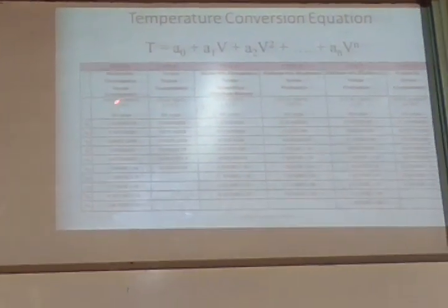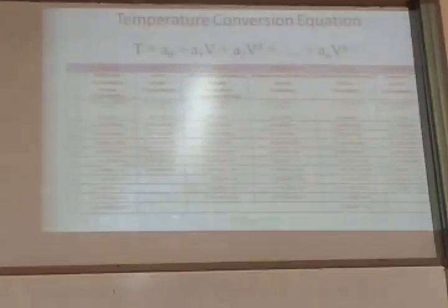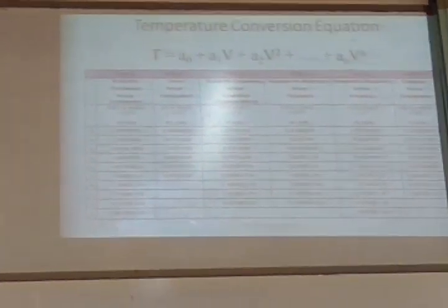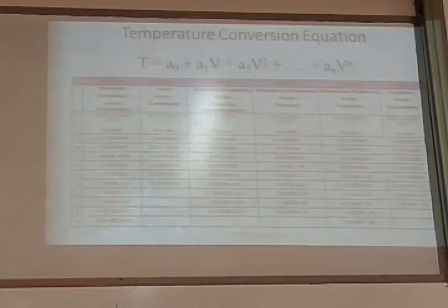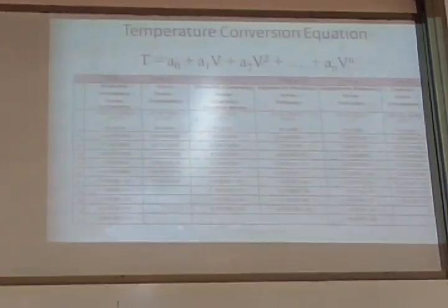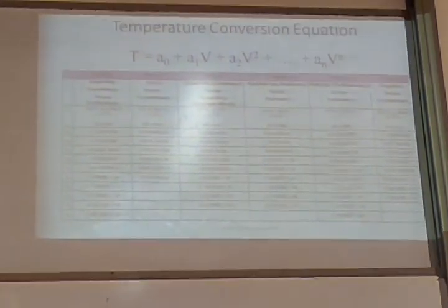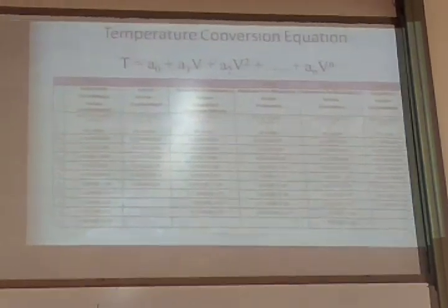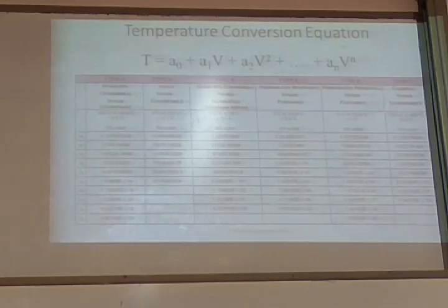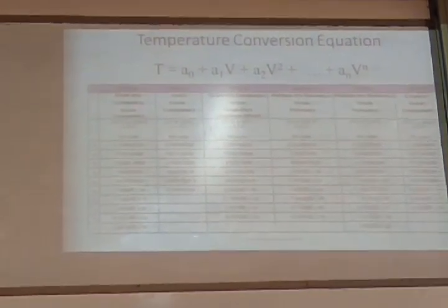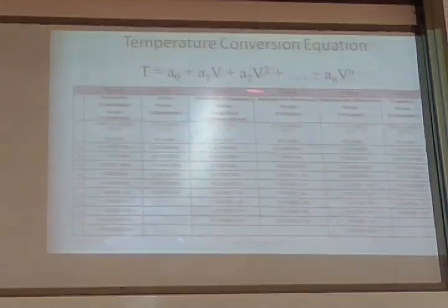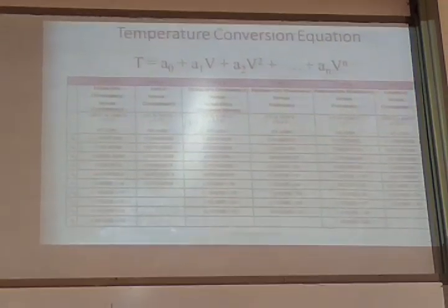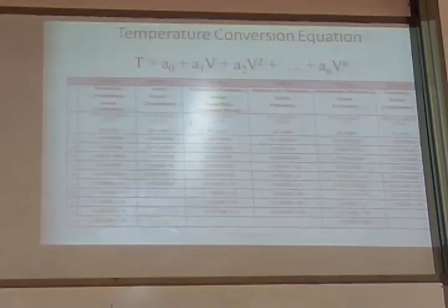For all of that, of course, here they have given the coefficients. There are graphs available. You will be able to see for this graph the voltage output that you will get for this much temperature difference. So from there, you will understand copper and iron have very low voltage compared to these combinations. These combinations are standard combinations which people have found to give high voltage output for a given temperature.